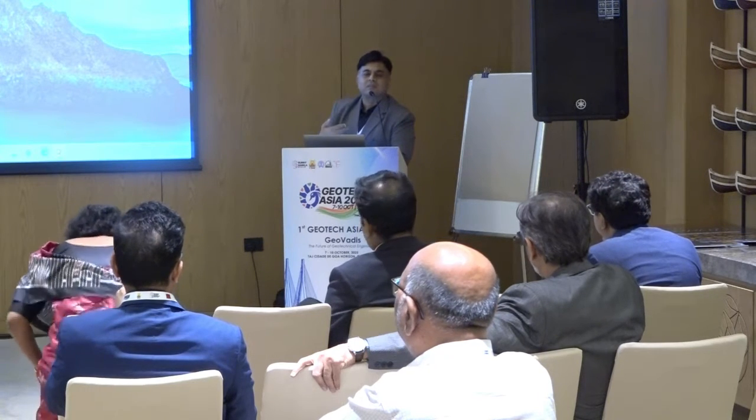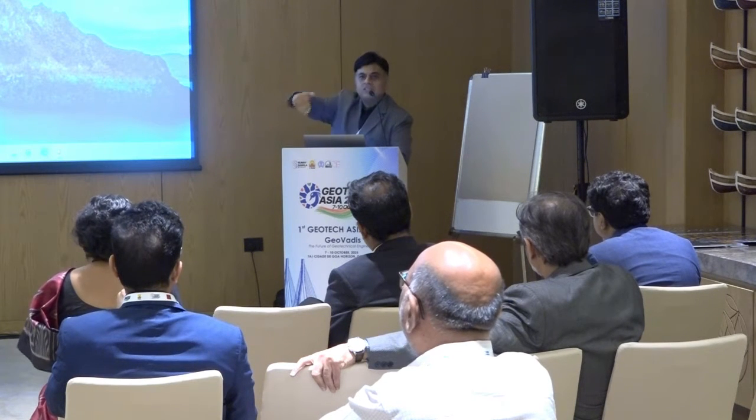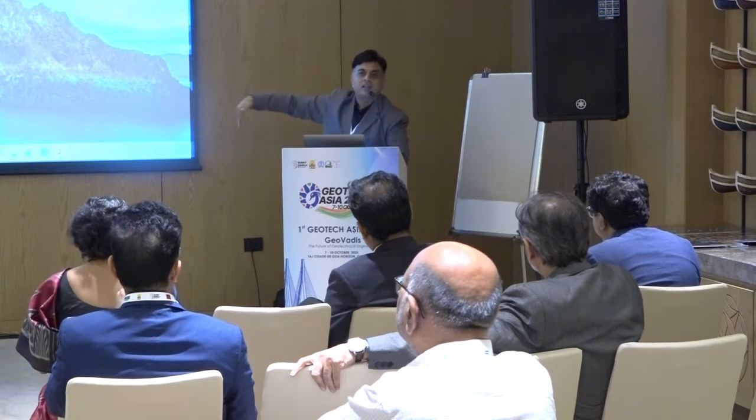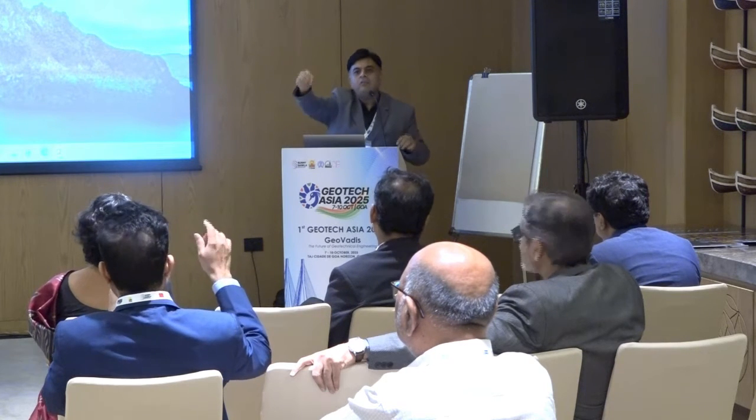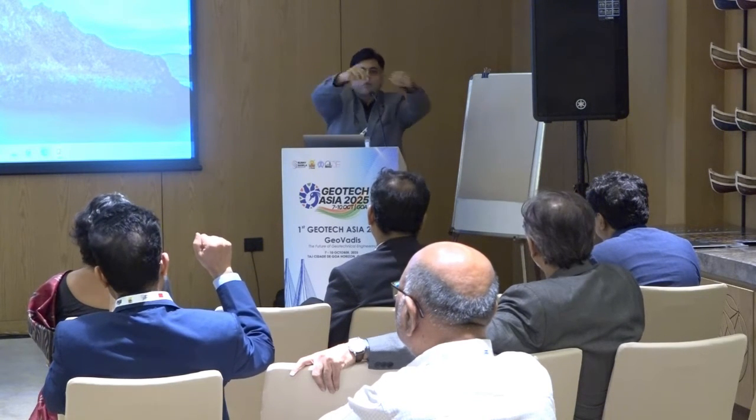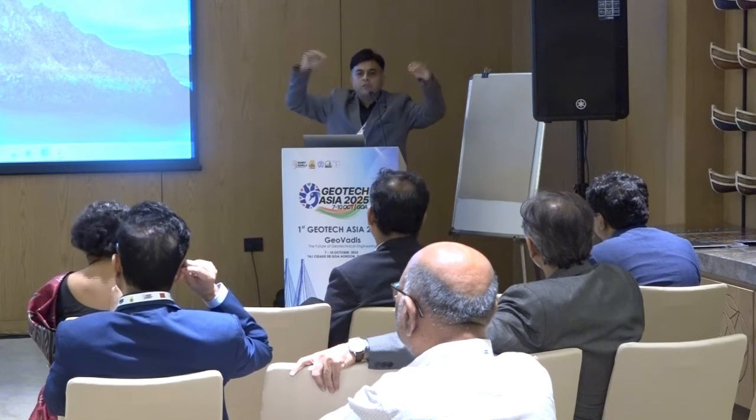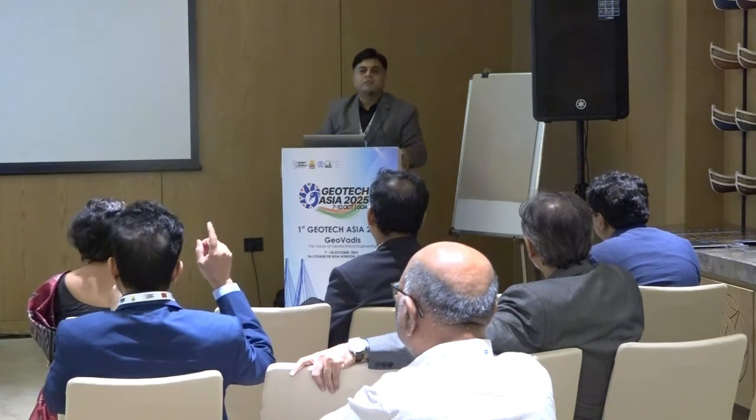Sir, I'd like to share my experience because previously I was working as a GC in Lucknow and on Chennai Metro also. What I've seen is that you can stagger them. It's not required to put them in a line. Wherever you get a space, put it there. There is a general practice that people say they have to put it in a line, and only then will they compare. It doesn't matter. Even if you get a point cloud on a map which shows you settlement, you can very well draw the drafts afterwards.